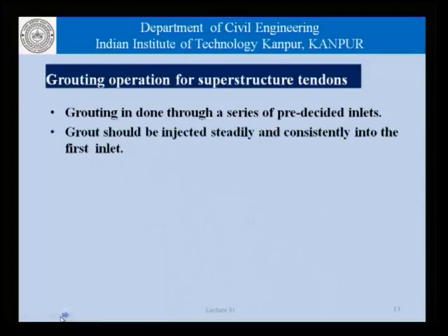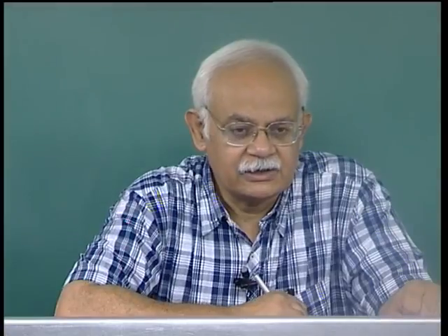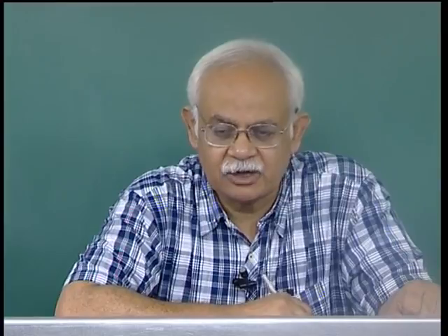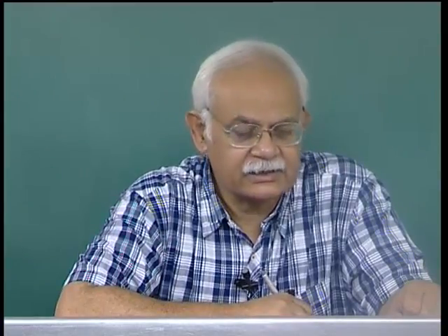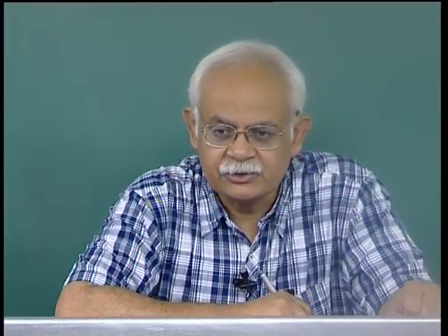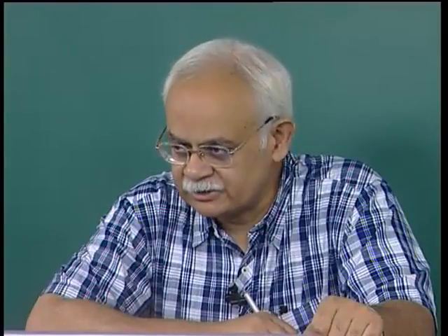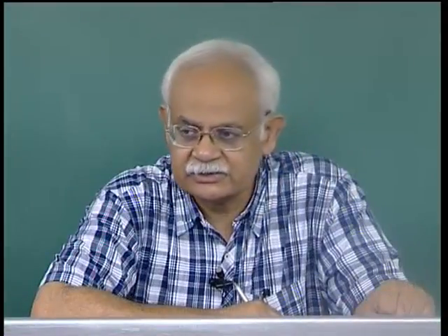Grout should be injected steadily and consistently into the first inlet. So, we cannot have an intermittent supply of grout. We cannot just grout a little bit, stop and then start grouting again. That unnecessarily leads to air pockets in the grouting systems, and that is very highly undesirable. So, we must ensure that the grouting is carried out steadily and consistently once the operation has started.